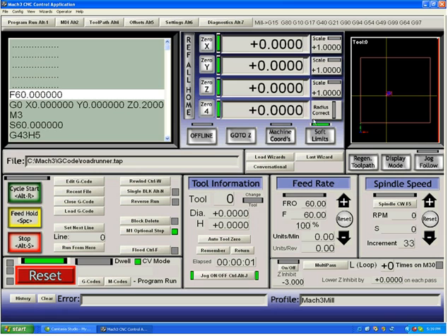I like to. If I was at this point to jog, because the system knows where my home switches are, if I was to jog towards a home switch, my axes will slow down as I approach 0. And you can see that the system just stopped, telling me that the movement was aborted because I hit the 0 point. If I look at my machine coordinates, I jogged it to 0.